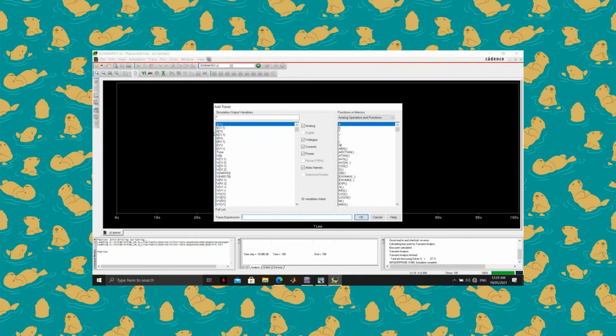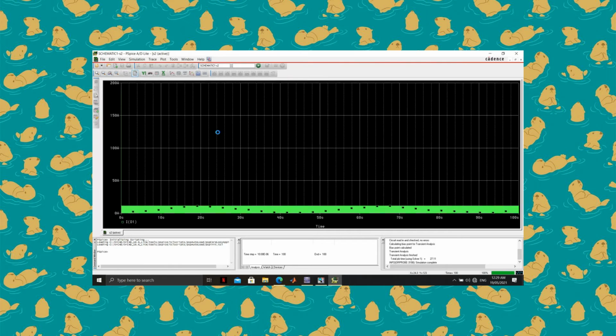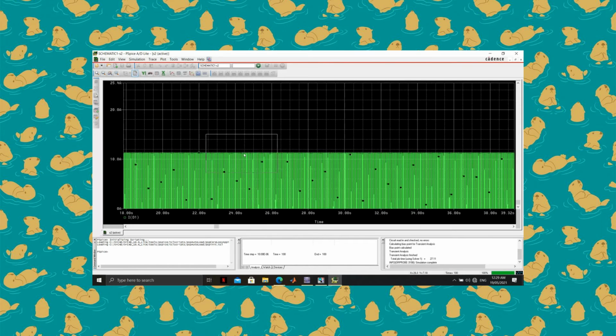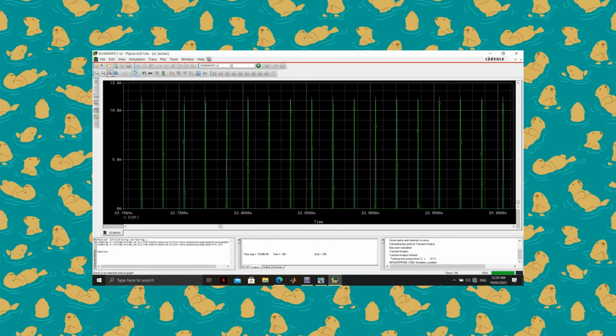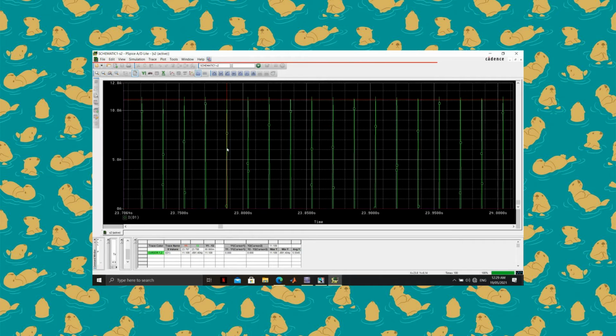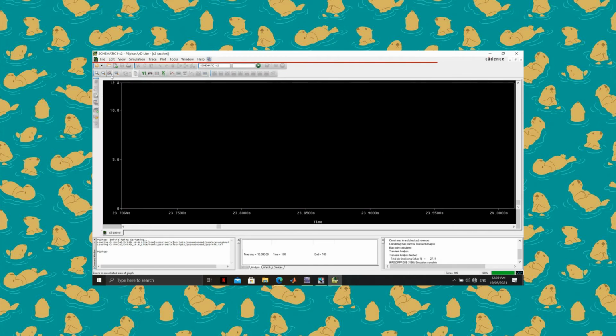First, we would look at our diode current. To be able to zoom in, we can see that it is now steady. So let's zoom in. There, you can see that the current peaks are almost the same in value. So, measure 1. Our recorded experimental peak diode current is 11.109 amperes. Next, delete.